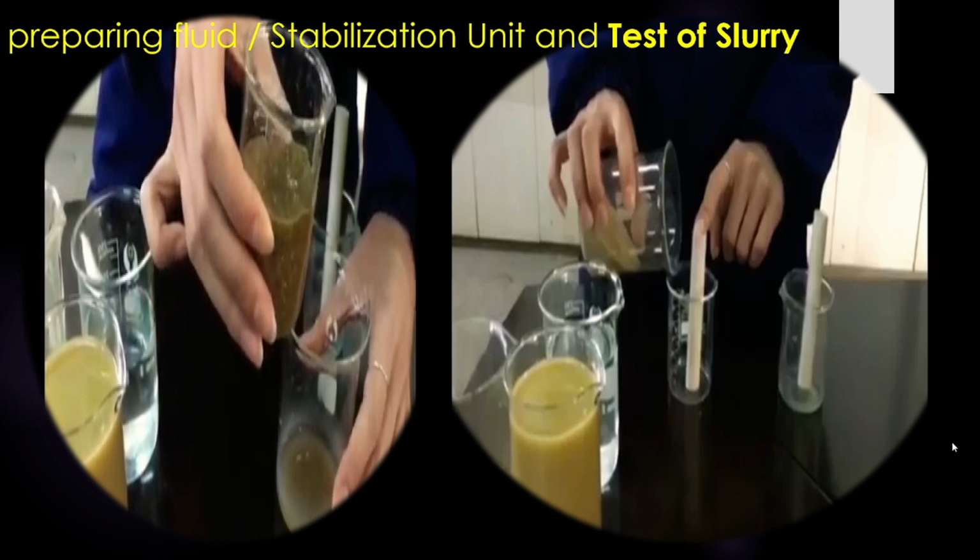This is crucial to prevent soil collapse before and during the concrete pouring. If the borehole wall collapses, loose soil can compromise the pile's quality and lower its bearing capacity. The sodium-based bentonite works effectively because it swells in water, forming a stable double layer on the soil particles. This property maintains slurry consistency, adapting from gel to fluid under disturbance.